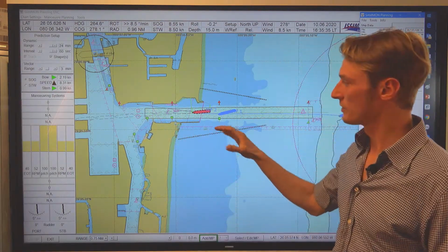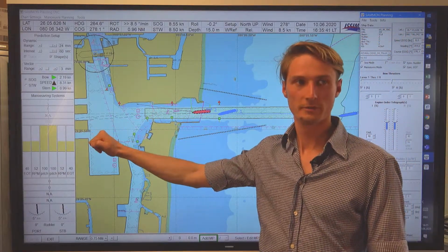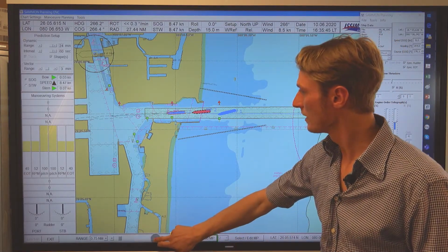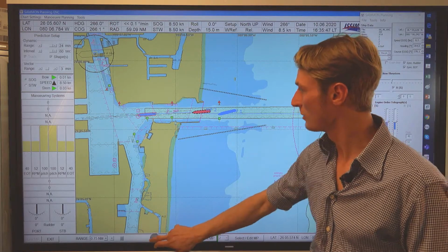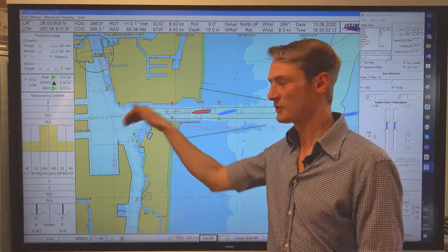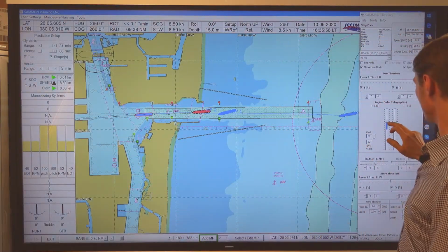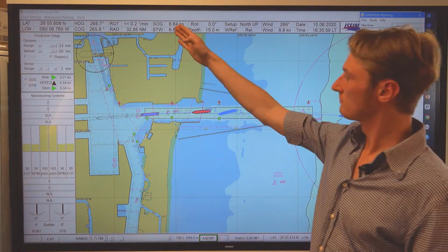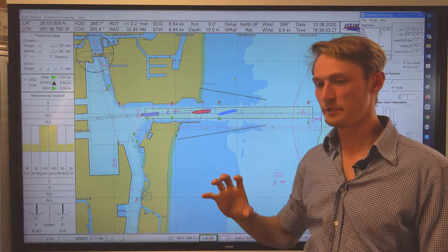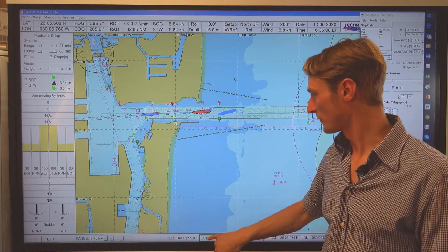The next aim, of course, is to reduce the speed and then to initiate a turn to port side. That means we move on, and as we did not change our engine setting, we still sail with a speed of 8.5 knots, which is a bit fast, of course, to initiate the turn, that's clear. So let's go back to, let's say, set 3. 7 knots, still pretty fast. Anyway, I want to keep it to demonstrate different effects of turning or different impact on the turn.